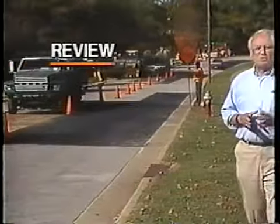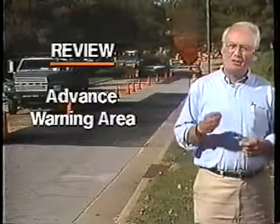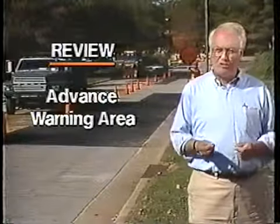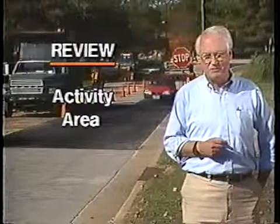As a review, these are the 4 parts of a traffic control zone. The advance warning area alerts the driver that there's something ahead that demands his close attention. In the transition area, traffic is shifted or moved to eliminate interference with work activities. The length of the taper should be computed or obtained from a table. The activity area is set aside for the actual work to be performed, to provide for the movement of through traffic, and to offer a margin of safety for both workers and motorists.